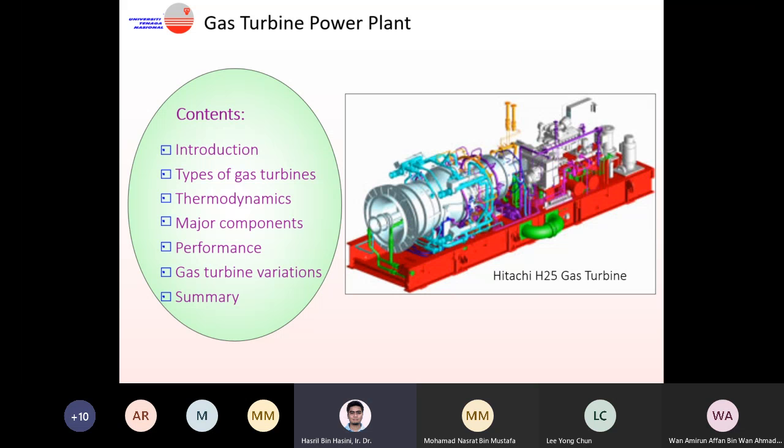Okay, let's have a look at the first factor that affects the gas turbine performance, the compressor inlet temperature. We are talking about the fresh air that comes into the compressor. In general, this one is very difficult to control, because you are talking about the ambient. We know that lower ambient temperature will result in a lower heat rate and better efficiency because of the higher pressure ratio. So how does it work?